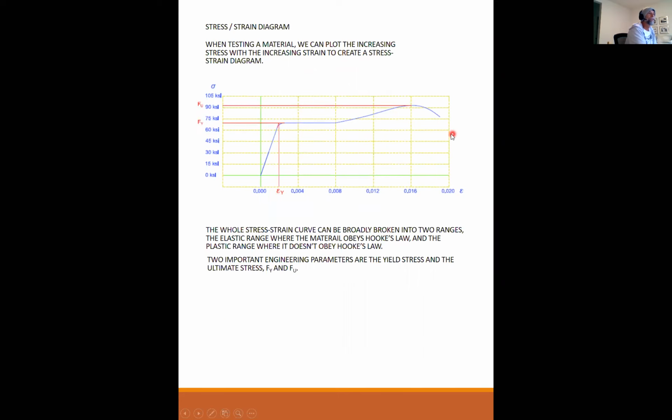In some material specs, you have to meet a minimum for F sub u. And in a lot of material specs, you have to hit a minimum for F sub y. And you'll also define epsilon y, the yielding strain. Generally, these parameters are defined by minimum values in ASTM specifications. Just in case you've never seen ASTM before, that stands for the American Society for Testing and Materials. And they publish zillions of different standards for all kinds of different materials.